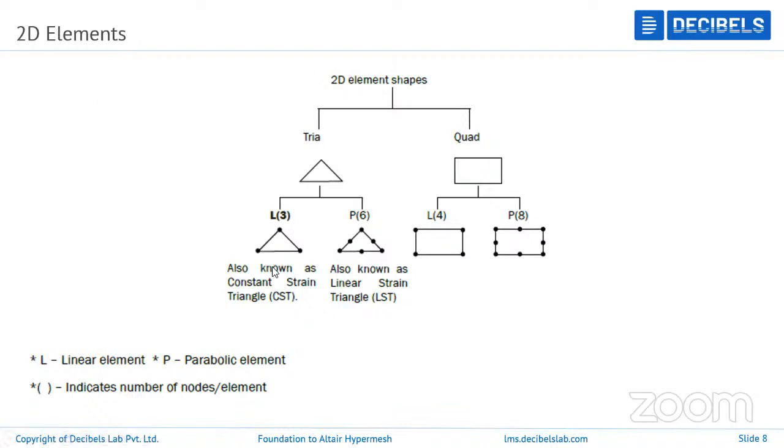When it is a first order element, the number of nodes is less, but the element count will be the same, with only the defined set of nodes. But when it comes to the parabolic element, one mid node is going to be added in between the corners of the element. But the element count will be the same for both cases. These two are the shapes that are sufficient to create any kind of mesh for any geometry.